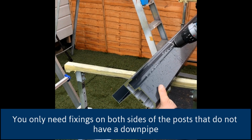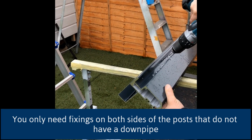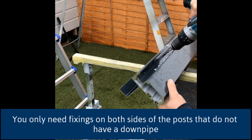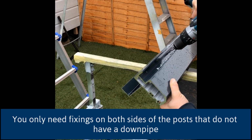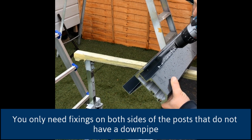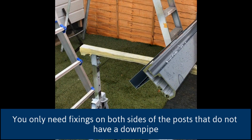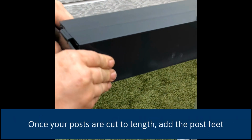Please note, you only need fixings on both sides of the posts that do not have a downpipe. Once your posts are cut to length, add the post feet.